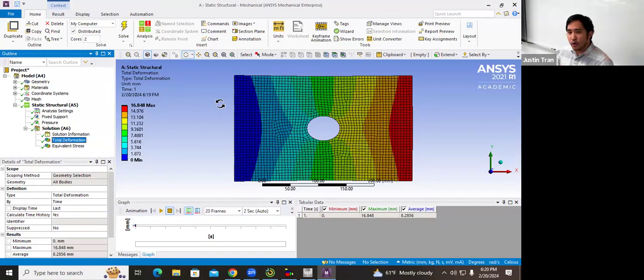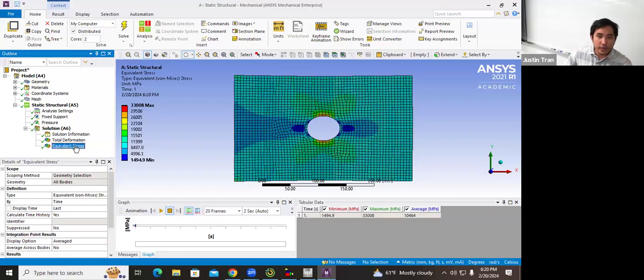And so I know all you see here are just 7 colors. But each color here represents a range. And so you can see here, everything in the deep red is between 16.85 and 14.98 millimeters. Okay. But the colors here indicate where all the deformations are occurring in this case. Okay, and then you can do the same thing for the stress.